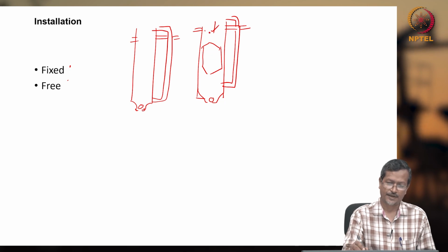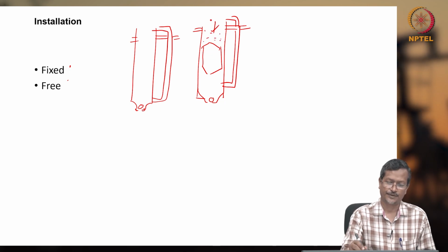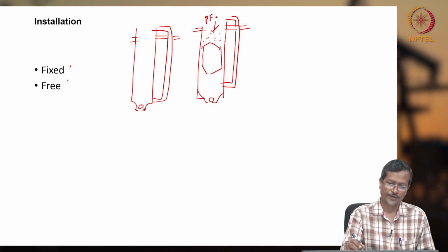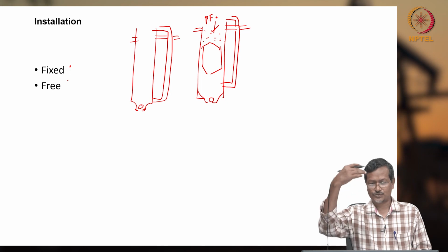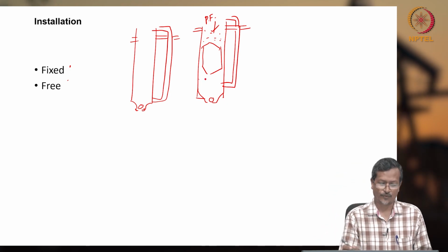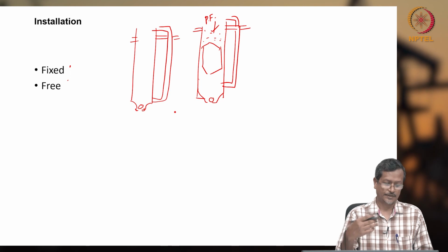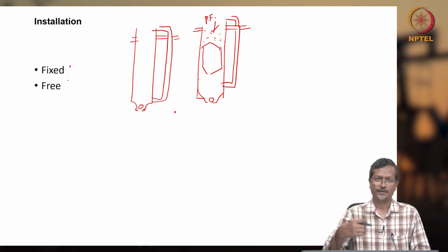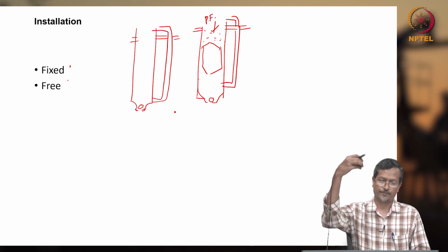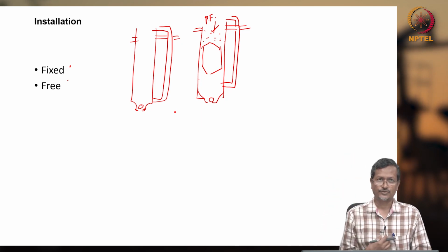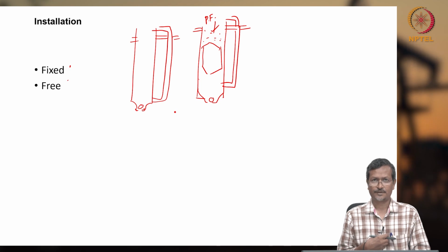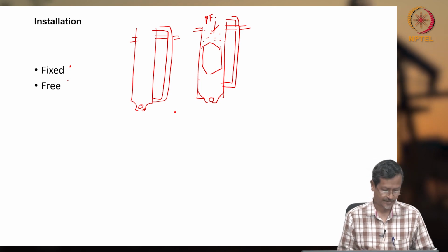So the pump is in, and you are giving very high pressure here. Power fluid you are giving. Power fluid you are pumping, and the pump is going down to your exact location. So this is actually the free type installation. When you want to install, just using power fluid you pressurize, and the system will move. So normally this free type system will not be used for your engine pump type system. It should be used for your jet pump type system.